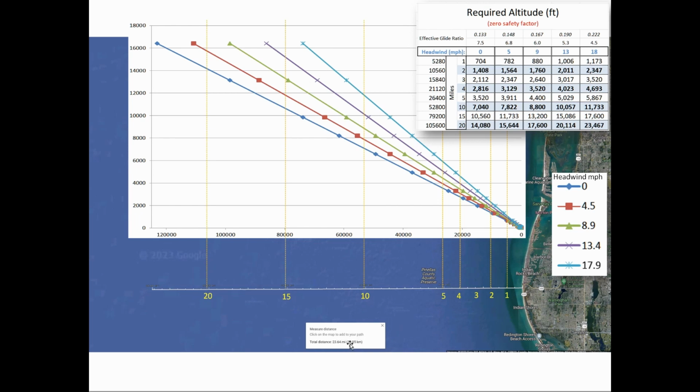And you can see down here, and these are mile 1, 2, 3, 4, 5 miles, 10 miles, 15, 20 miles. And then I tried to align this graph, obviously. And then I went into Excel to get the exact numbers here for these yellowed ones. So 1, 2, 3, 4, 5, 10, 15, 20. And this is again with our glider ratio of 7.5 to 1. And you can see I did a little math here and showed the headwind changes your effective glide ratio.